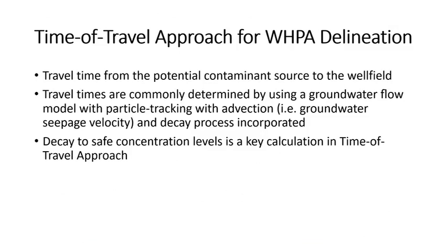Alright, let's resume. This is the time of travel approach for wellhead protection area delineation. What we do here is calculate the travel time from the potential contaminant source to the wellfield. We are essentially talking about the travel time that will allow for sufficient attenuation. Okay, so this is about travel time for the sufficient attenuation process to occur.